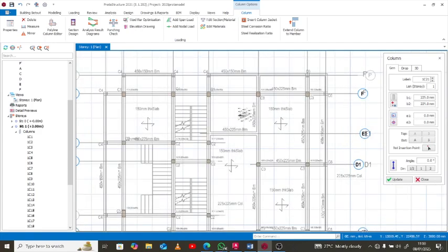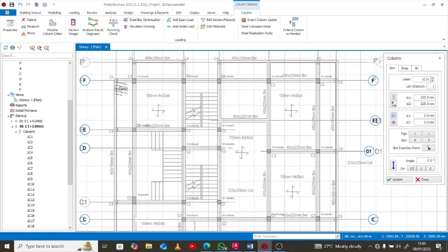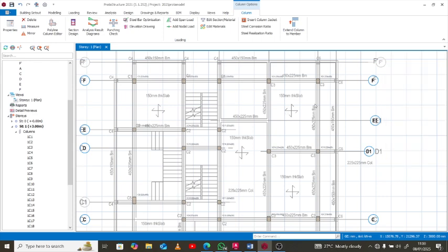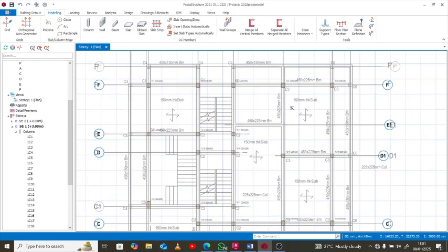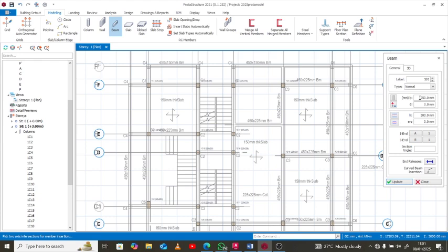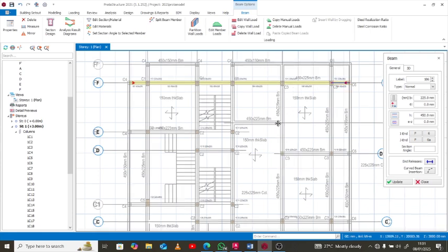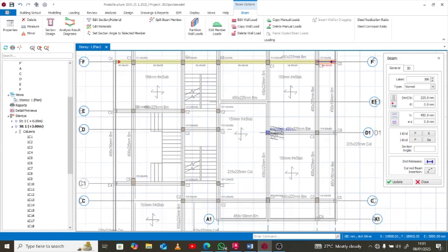All right, because this is the first floor arrangement, we'll just have to put the beams that we have here, then we'll go back to other things. So let's go for the beams. The beam is 450 by 225. And you must understand the theory of primary and secondary beams if you need to do things correctly.